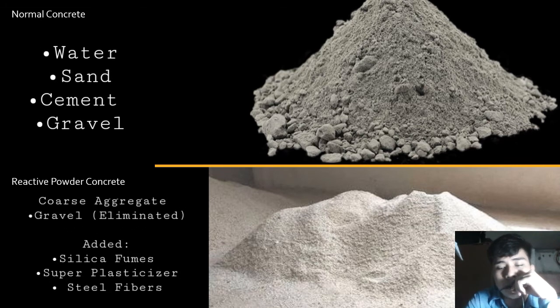The chemistry behind the RPC, or reactive powder concrete, is where the dissolved cement produces hydroxyl ions. The hydroxyl ions come from the cement that is combined with water, and that process is called the hydration process. The hydration process can also lead to a precipitation reaction, where the cement produces a huge amount of silicon and calcium in a solution. The precipitation reaction also produces new solid product that coats current cement and other aggregates.